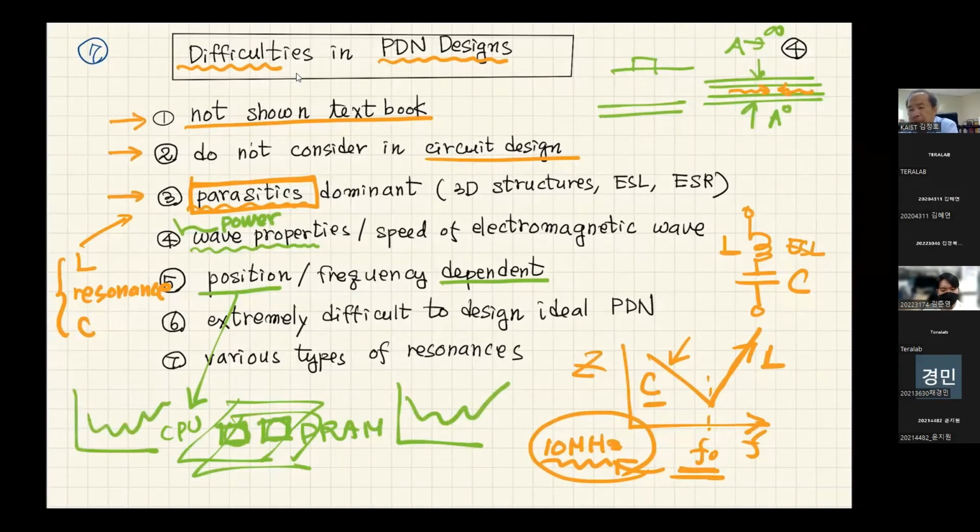You remember that in transmission line, length is controlling the skew and delay when we are sending very high frequency signals. So length combined with frequency, speed of light is controlling the delay, and in some part of the waveform of high speed digital at the receiver side. And likely PDN impedance is also position dependent. That is not the usual concept of circuit design.